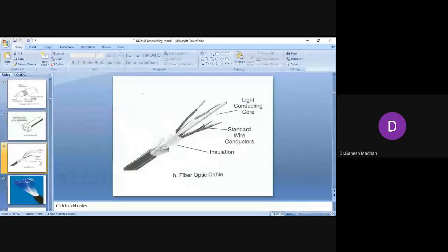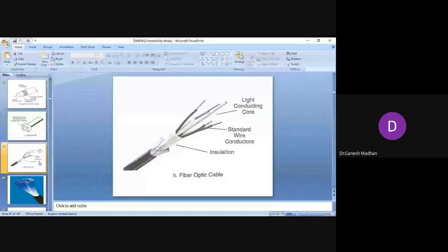So this is a fiber optic cable where you have a number of glass strands put in a plastic tube, and then you have a central strengthening member, and you have insulation covers, and of course you have an outer plastic or PVC jacket. So you have around 5 or 6 optical fiber strands. The dimension is almost around 100 micrometers, the size of a human hair.